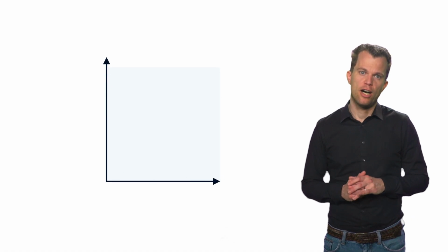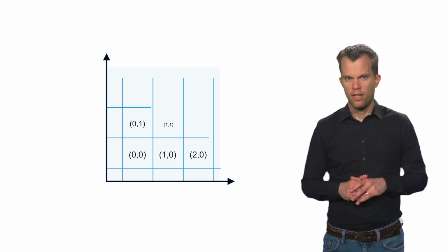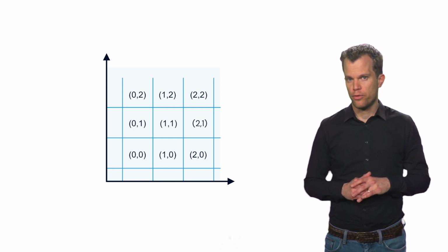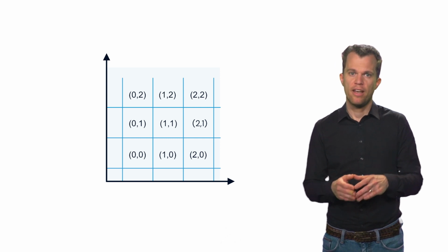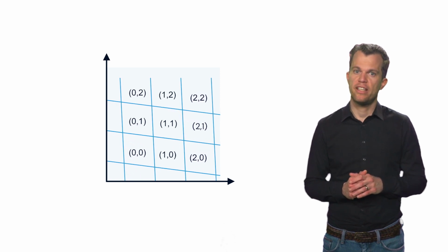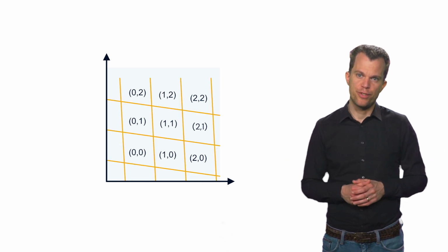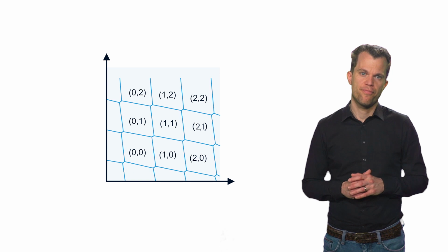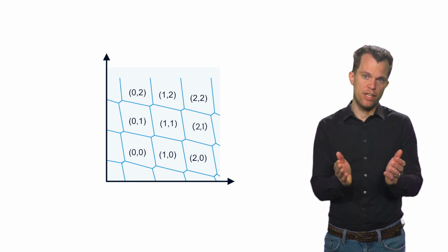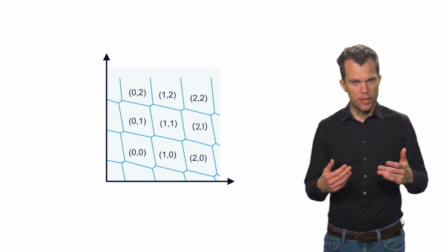Now, let's see how measuring a quantum dot works in practice. We first consider a double quantum dot. In the case that there is no capacitive crosstalk, the energy levels corresponding to the electrons in a quantum dot are spaced horizontally and vertically in a so-called stability diagram, where the axes are spanned by the gate voltage. When there is finite crosstalk, which is always the case in real scenarios, the lines start to bend. In addition, there may also be an interdot coupling. The capacitive interaction between the electrons in the two quantum dots results in an anti-crossing in the stability diagram.